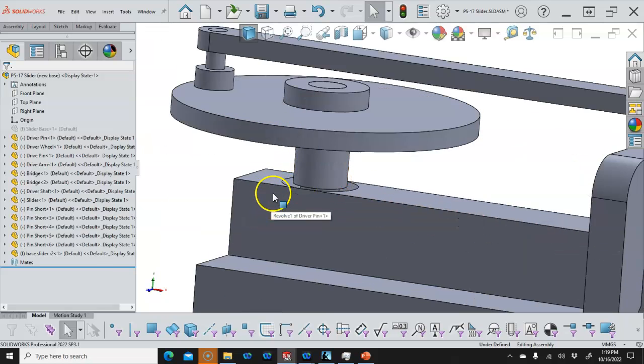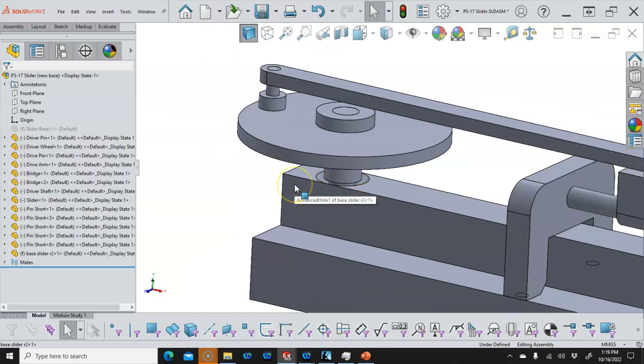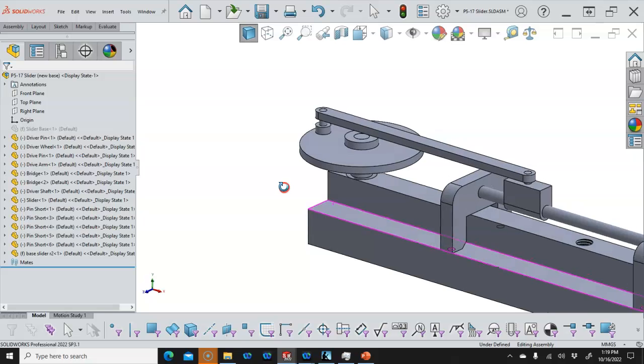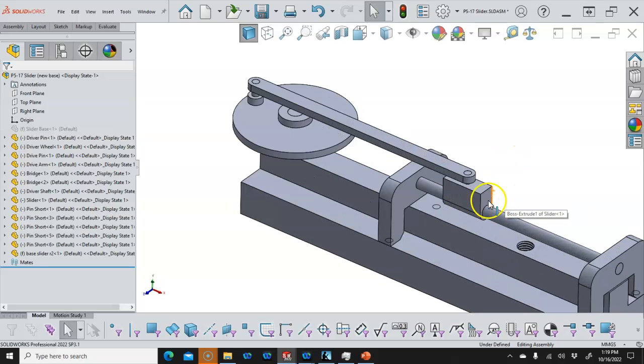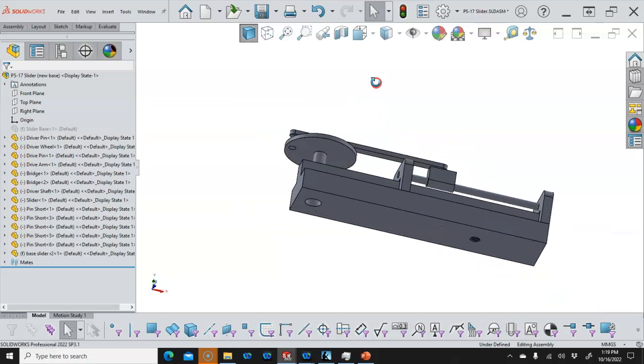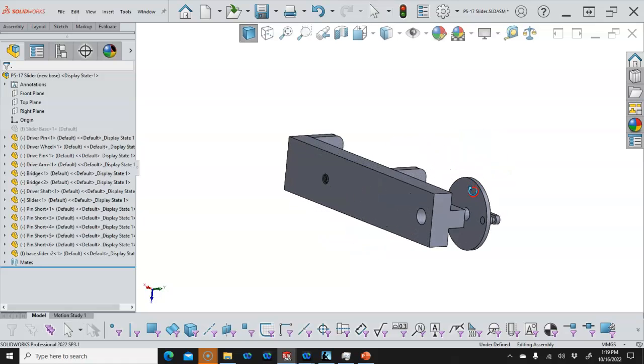Was that a good idea? Do I need to go back and change that? Maybe make the adjustment to the counterbore on this side so that has some fit. Are we going to put in bearings as this turns and moves, and we start to look at the dynamics, how it goes through the motion? What is available to make adjustments, and if we're driving this as a motor, we really don't know the orientation that this is going to sit on in the final.